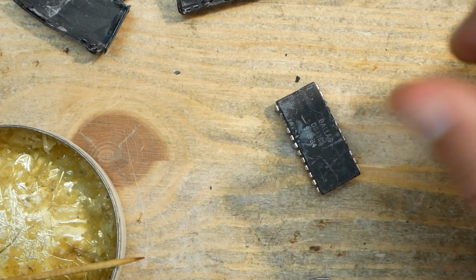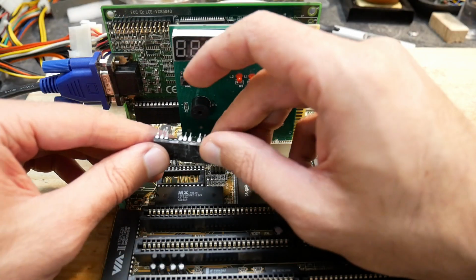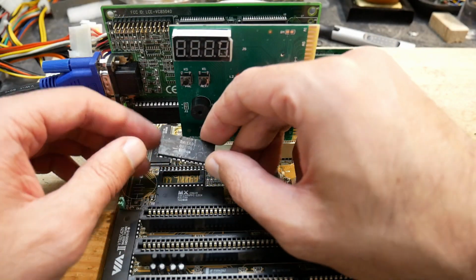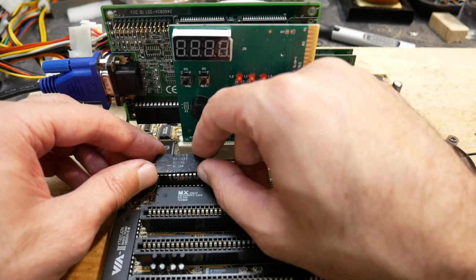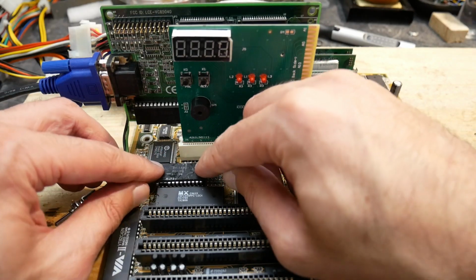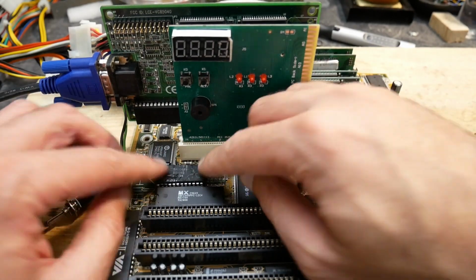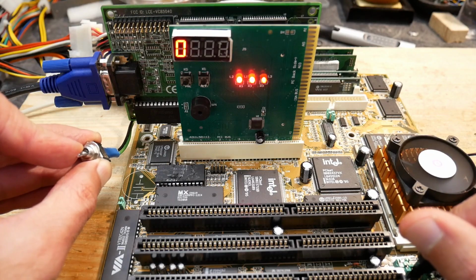So my first try was a Dallas DS1287. Some of the pins on the IC are flipped up, and if you try to bend them down, they break very easily, so you might need to resolder the pins. However, I tried to run the IC as is, without the crystal oscillator or a battery connected, and the board was dead.